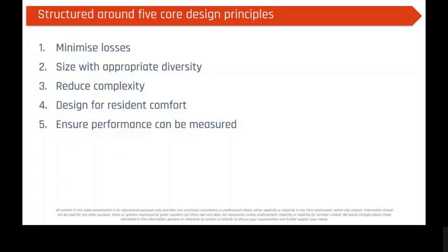It's been quite challenging. The industry is oversizing. So when we oversize a heat network, that peak load profile that I showed you, where we spend very little time at the actual peak load, if I make that oversized by even 300%, I'm exaggerating that profile even more and putting even more kit that's sitting there doing nothing.